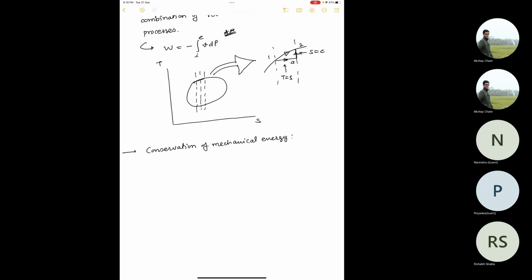But one part that I want to highlight is this equation that was derived in the class. It is for mechanical energy, and it comprises kinetic energy, potential energy, and I think they call it flow energy or flow work. Those three parts are here. Keep in mind that temperature effects are not here. Temperature effects are considered in internal energy. So that's why when you wrote the first law, you wrote E as U plus KE plus PE.